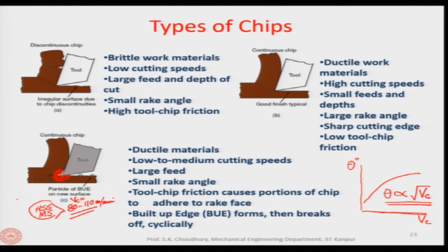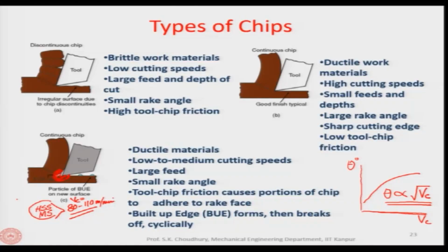The built up edge is probably only useful when a tool with a built up edge can be used for rough turning. For example, if we have a very hard surface on the top of the workpiece that has to be removed before the normal machining process happens, then a tool with a built up edge can be used, because this built up edge material is strain hardened and very hard.